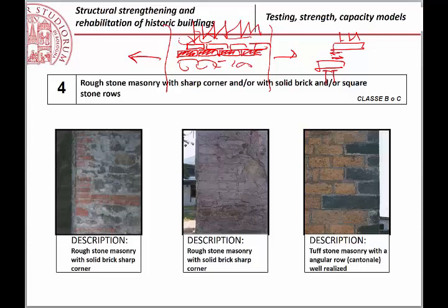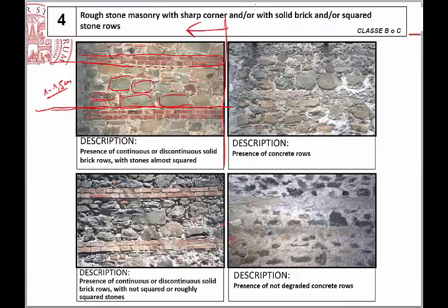Okay? So, with 2 bricks, the vertical loading is giving you friction, and the friction means possibility of supporting traction. So this realization is improving significantly the quality of the masonry in this case. You see in these two pictures.